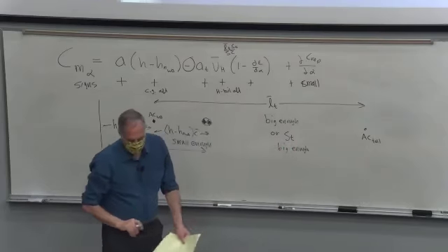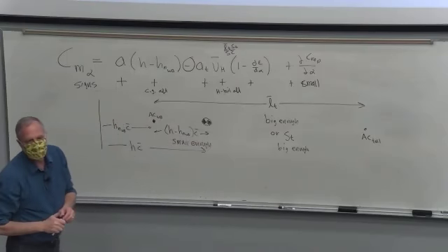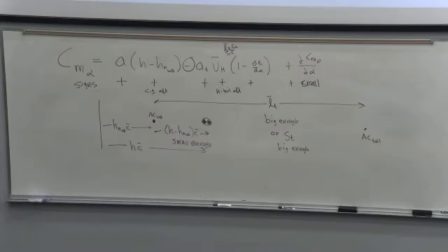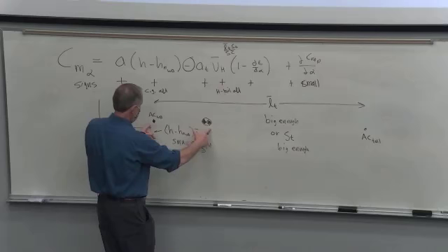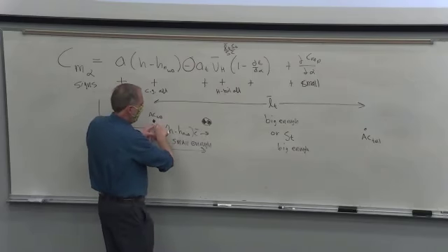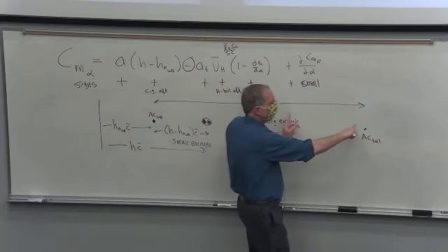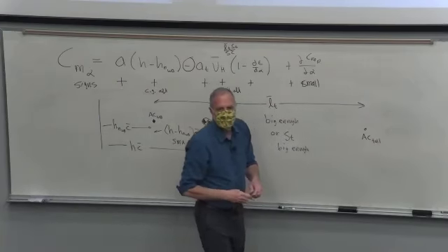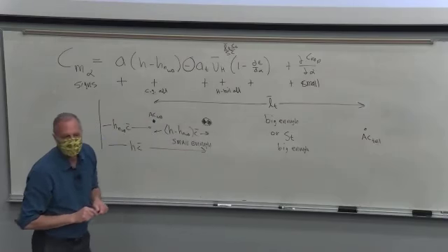So that tells you the secret to design. That's not a secret. The strategy to making sure that your airplane is pitch stable is that the CG is close enough to the aerodynamic center of the wing body, and you have a big enough tail far enough aft that you get a negative number out of this.